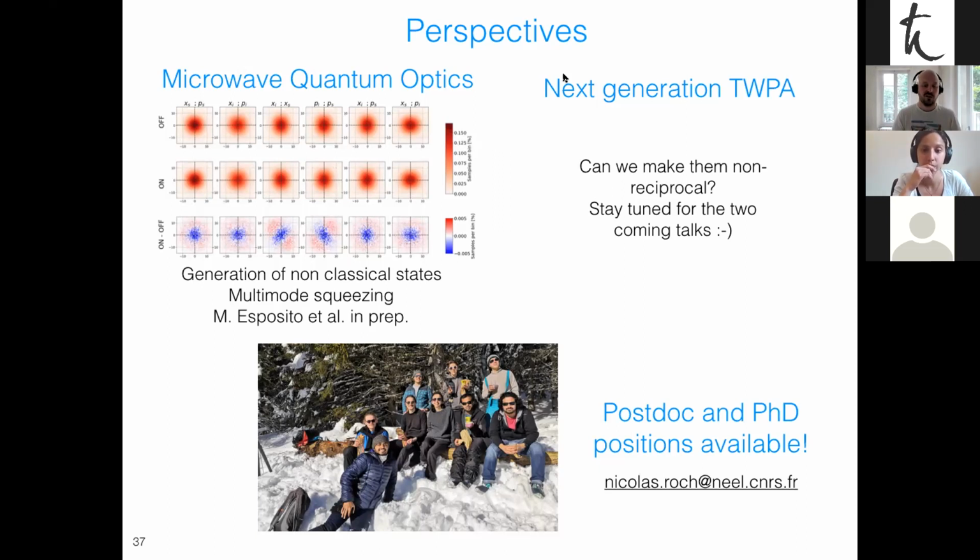Of course, life is not as easy. What happens in any parametric device is that usually you have other processes. So you might have three-wave mixing, you might have frequency doubling, you might have frequency sum. And these other processes might combine with the process you want, and this will degrade the noise properties of your amplifier. So to answer your question more precisely, with band engineering, or dispersion engineering, you might be able to kill these unwanted processes, and you might be able to get better noise performance.